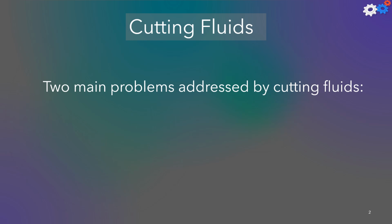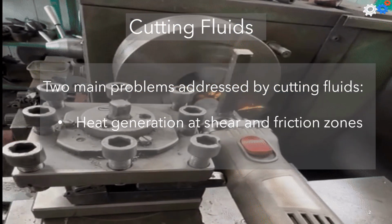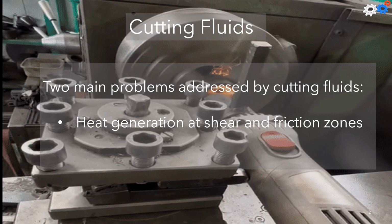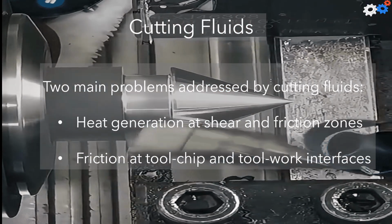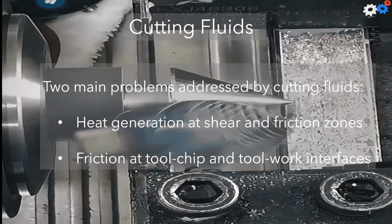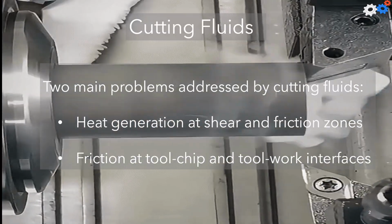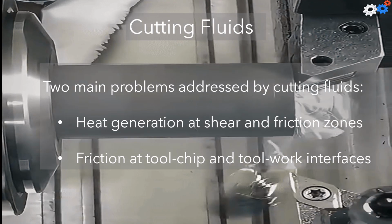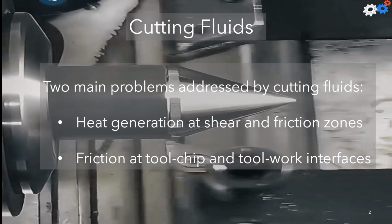The two problems addressed by the cutting fluids are, first, the heat generation at the shear and the friction zones. Second, the friction at the tool-chip and the tool-work interface. So the cutting fluids are any liquid or gas applied directly to the machining operation to improve the cutting performance.